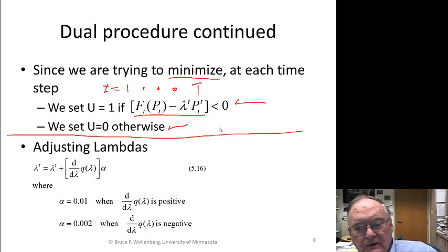So what I end up with is I say, okay, here I turn the unit on, and then maybe I keep it on, then I turn it off, then I turn it right back on, then I turn it right back off, and then I keep it on for 2 periods. That's the kind of path. On, stay on, off, go back on, go down, and so forth. If there are minimum up and down times, you can apply them right within this up and down logic as well.